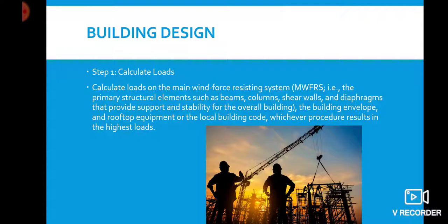In the past, architects seldom performed load calculations on the building envelope, for roof and wall coverings, doors, windows and skylights, and rooftop equipment. Neither did their structural or mechanical engineers, in large part as a result of not determining loads on these elements and designing them with adequate load resistance. Building envelope and rooftop equipment failures have been the leading cause of failure during past wind events.